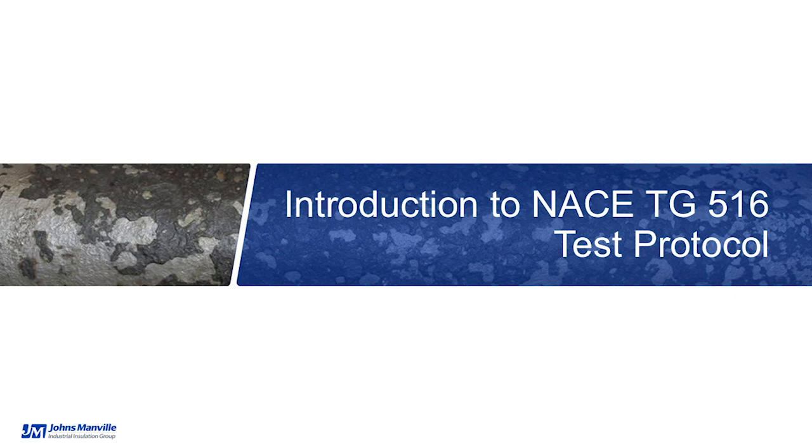We first presented results using the proposed NACE TG 516 protocol last year when we compared the CUI results with our insul-thin HT microporous blanket and a competitive aerogel blanket. Subsequently, after the webinar, because we received pretty good feedback from the engineering community and end users of our insulation materials, we decided to expand our testing using this protocol to 2 more of our products that we'll be reviewing this afternoon.